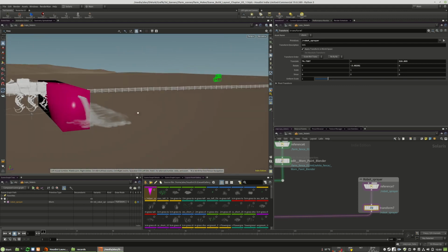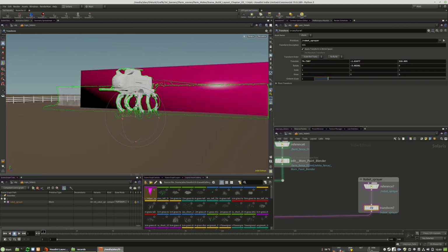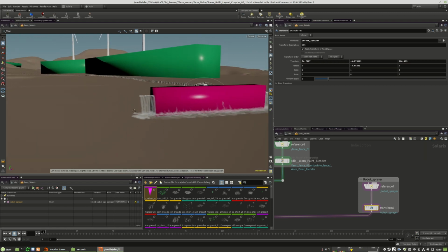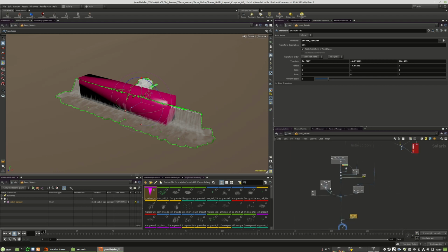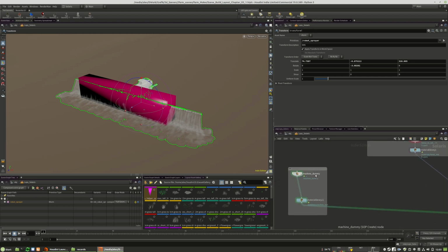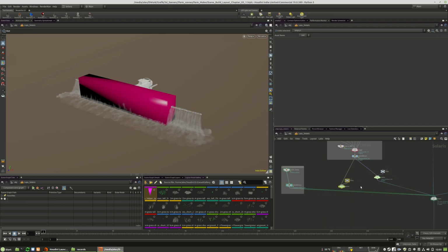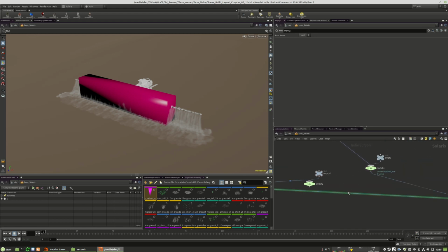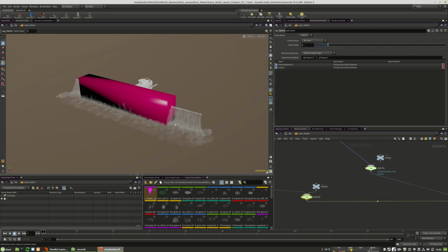We have to make sure that we are on the ground, but keep in mind we have some displacement. So we probably will move our robot a little higher, somewhere here. And we will deactivate our machine dummy somewhere here. So we will copy and paste this switch. And we will just turn it off.